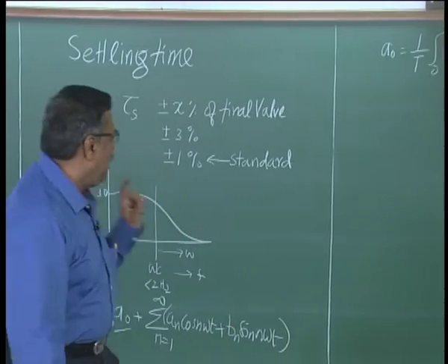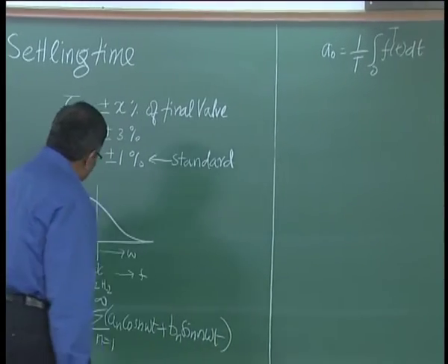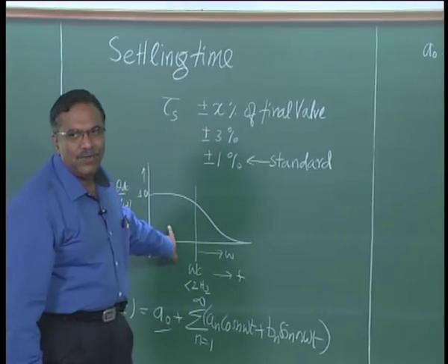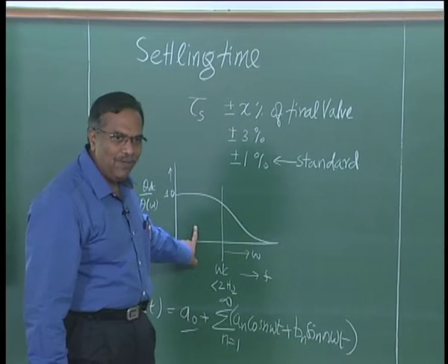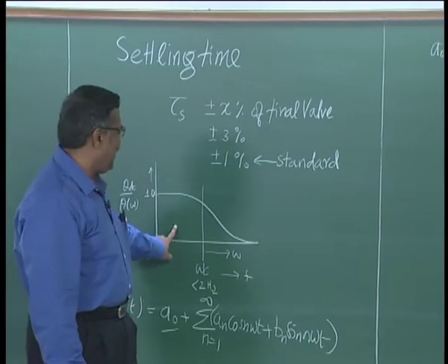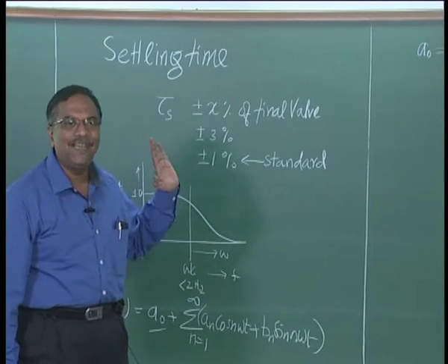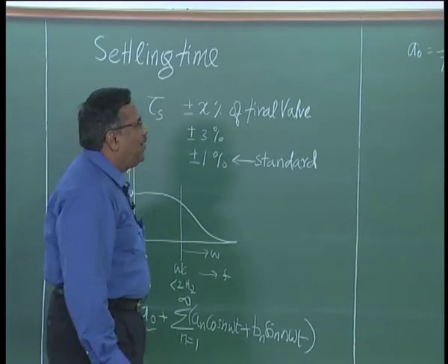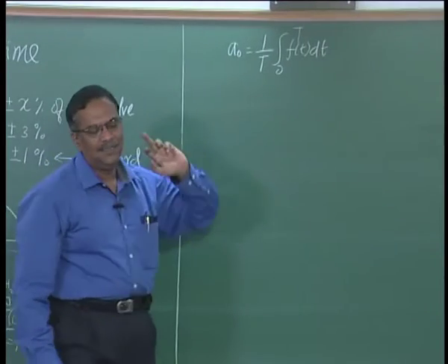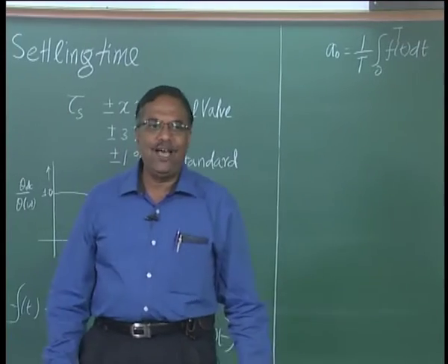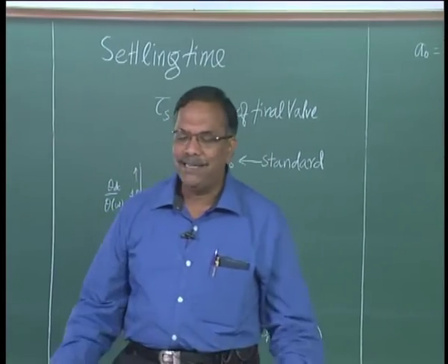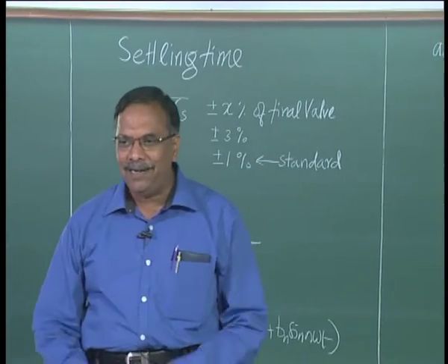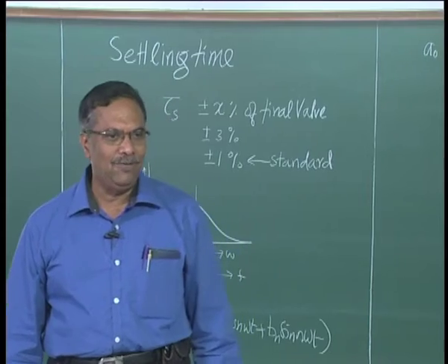So now we are going to link these two. My PMMC meter would respond only to very low frequencies, and I can get a stable reading only if I send a DC current. Now the DC value of any function is the average value of the function, 1 by T integral 0 to T f of t, which is nothing but the average value of the function.